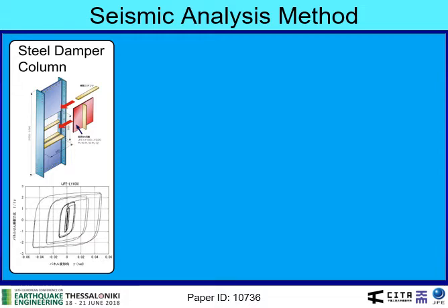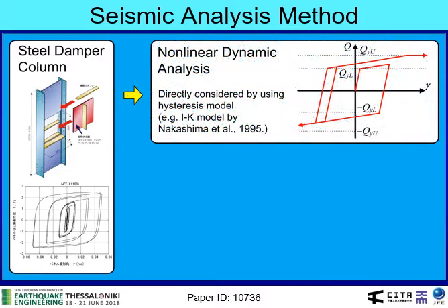So I would like to discuss the seismic analysis method. As I said, how to consider the strain hardening behavior is the key of this presentation. In the nonlinear dynamic analysis, this can be directly considered by using a proper hysteresis rule, such as the IK model proposed by Professor Nakashima in 1995.